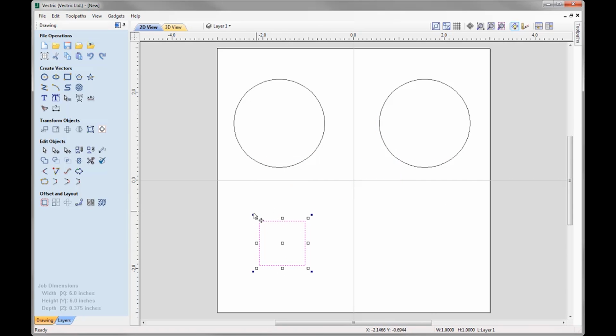I mentioned that we can also use the transform shortcut keys to rotate an object. So I'm going to take that handle and I'm just going to start rotating it and just going to type in 45, you can see that at the bottom, followed by enter, and it will rotate that for me by 45 degrees. So again, much quicker to do it this way than to have to go into the rotate objects form to then put in a number to rotate the object by. So let's just undo that.